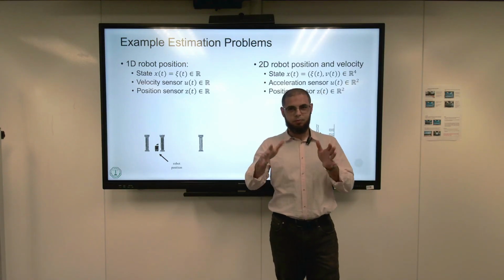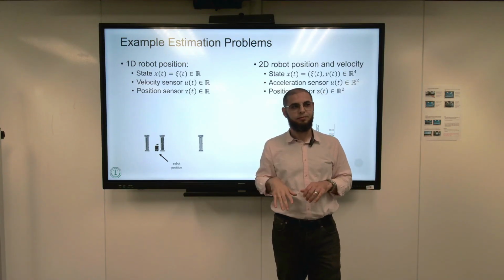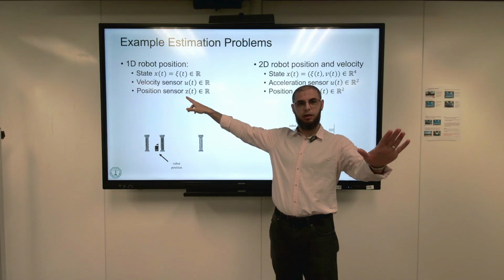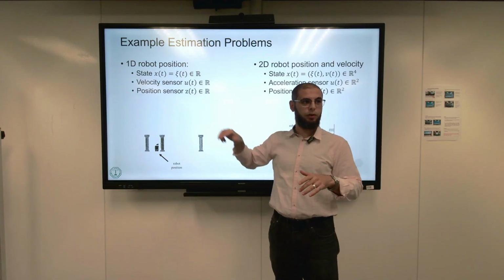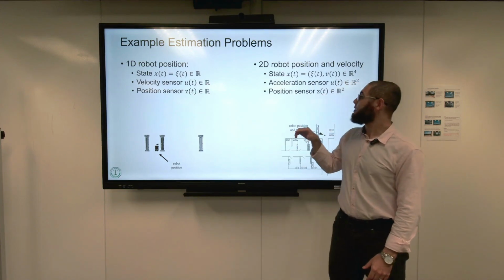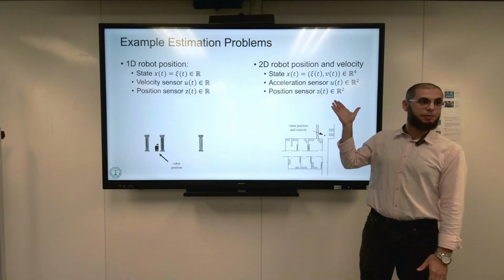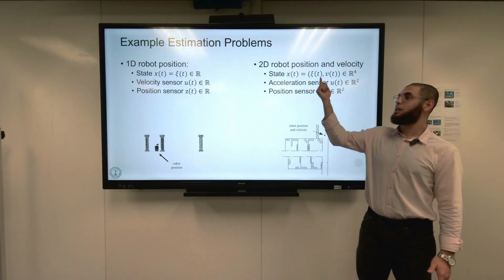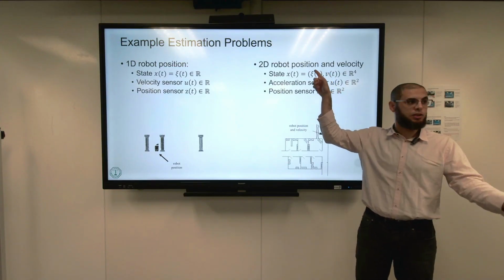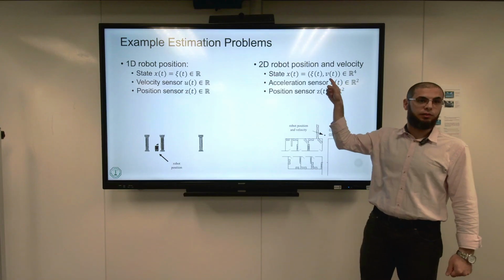Almost there. It's yes and no. So the answer is, you remember what we had in the position. I'll actually come back to that point. So I'll keep that question. I'll come back to it when we start talking about the lecture. And here you see, in this problem, it's actually clearer. I had a position sensor and an acceleration sensor, and I was able to get out of the Kalman filter more stuff than I'm just sensing. I got the velocity out of it as well.